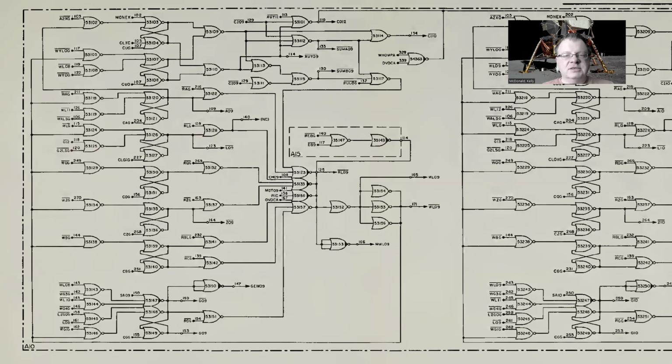Now, the Apollo Guidance Computer was designed with a concept of almost bit slicing for all of its registers. So there's four modules which contain all of the registers for the computer itself. And the way that they do it is that they implement all of the bit nines, in this case, for every single register. And you can see, here we've got an A register. So you can see the write signal here for the A register, and that's the actual storage element for the A register, bit 9. In this case, we've got the Z register. There's the storage element for the Z register, and Z register bit 9, and so on and so forth.